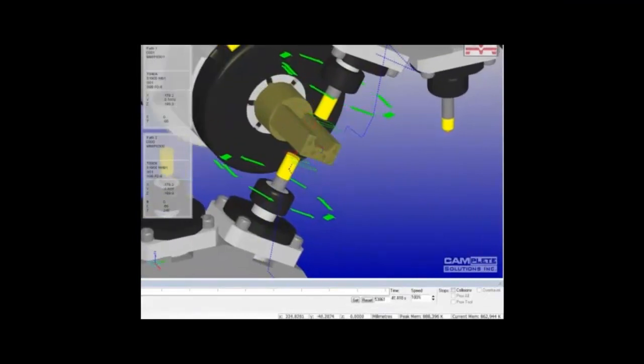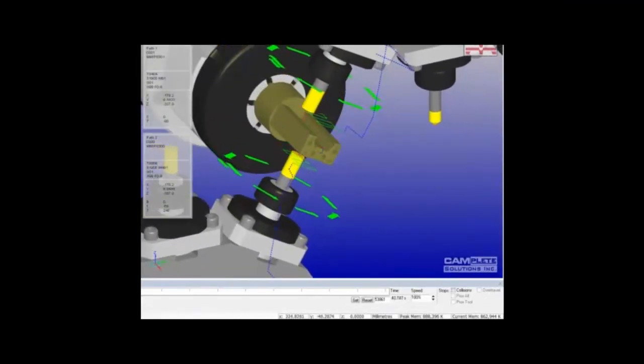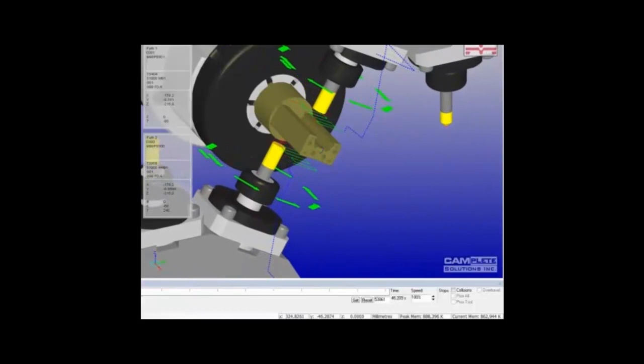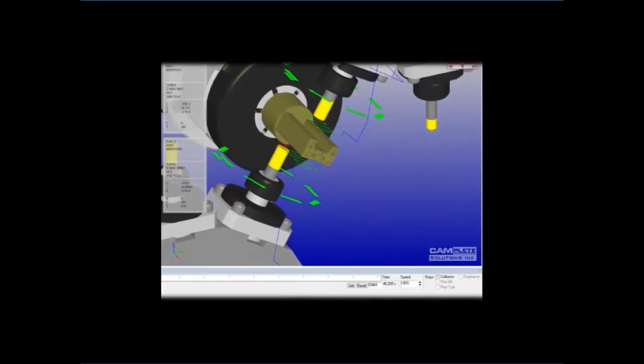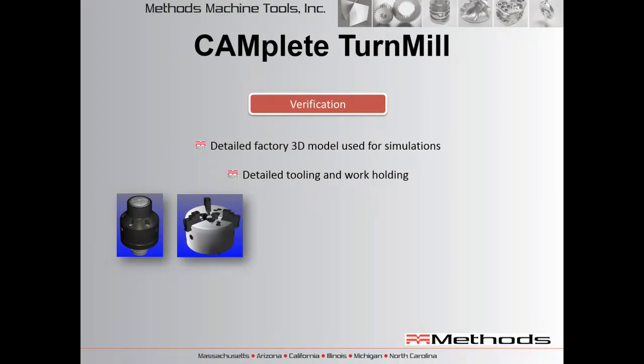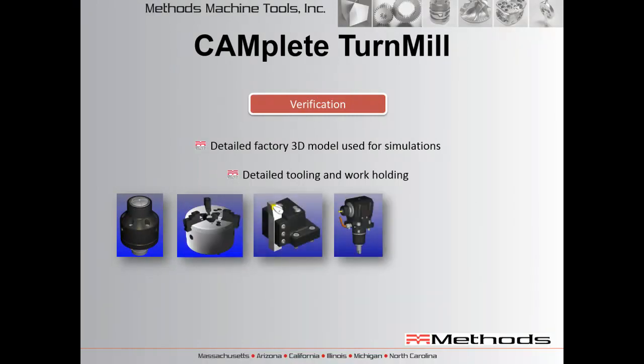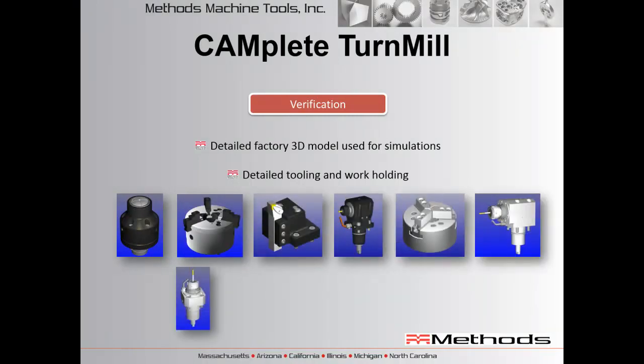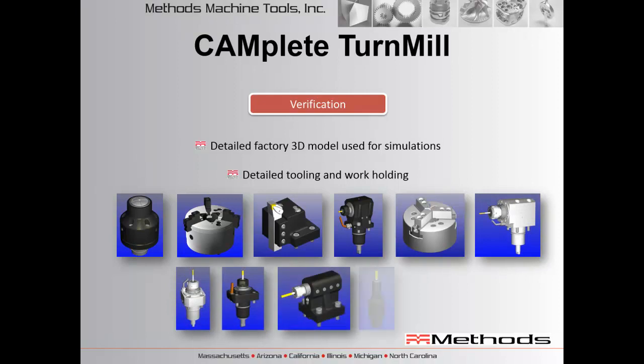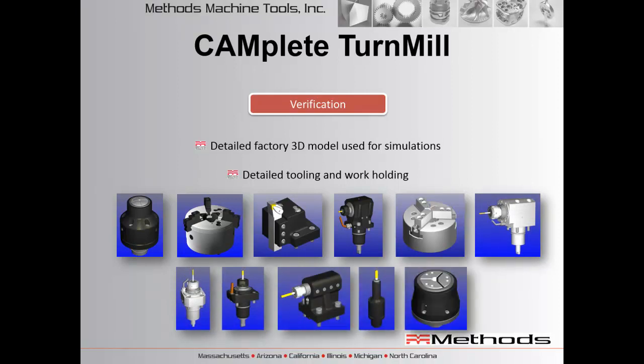Even from the milling standpoint, if you do milling on the top, you can pull it down, copy it, and you will be now pinch milling as shown in this particular video. We have the actual models for all of the holders for Nakamura. We have all of the collet holders and chucks and live tooling that you would use on your Nakamura lathe. These are all models from the people who build tooling, and everything is associative.